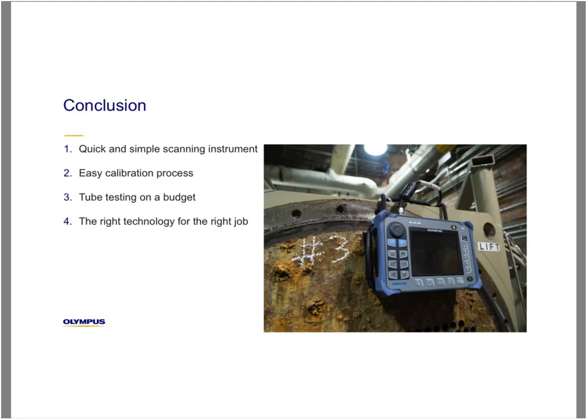And it also has the right technology for the right job, so you're not just limited to eddy current. You have eddy current, remote field, and near field. You can inspect any combination of finned, unfinned, ferromagnetic, non-ferromagnetic material with different diameters and different wall thicknesses. So it's really a versatile instrument.